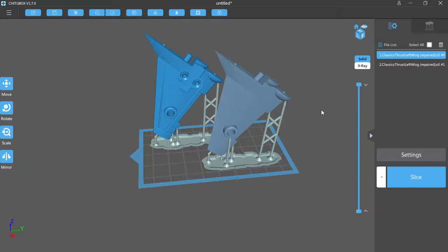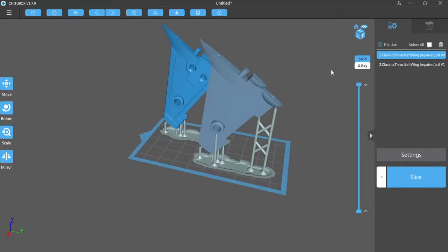Some people said they were using PTFE, like 3-in-1 PTFE lubricant, on their vats, not the bed. You want it to stick to the bed. Do it to the vat, not the metal piece that moves up and down. That's your bed.